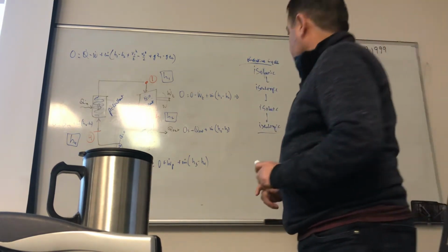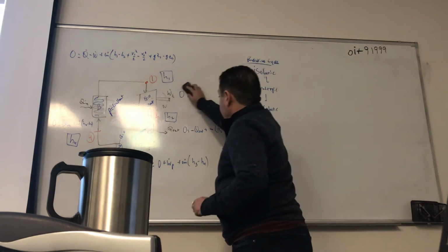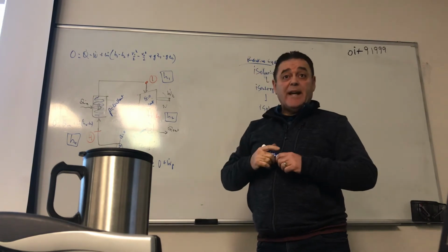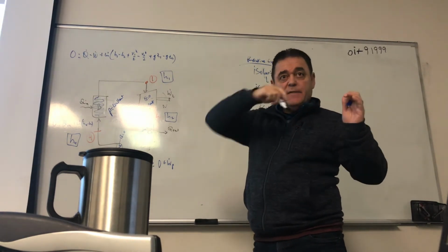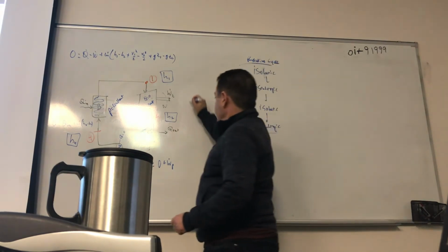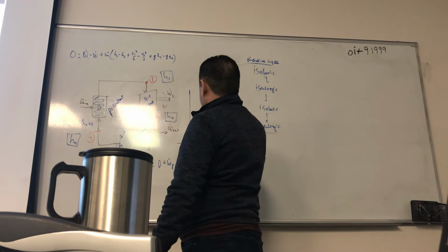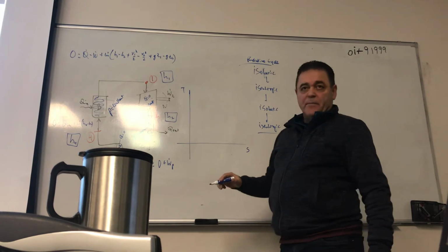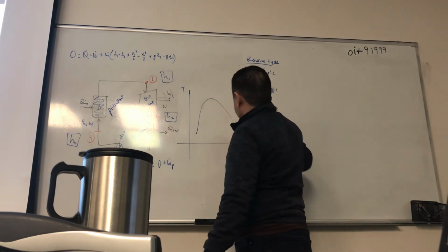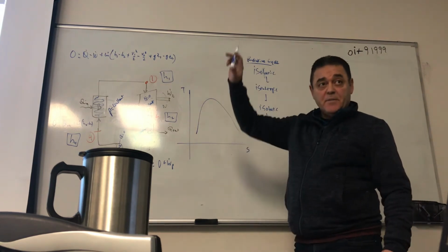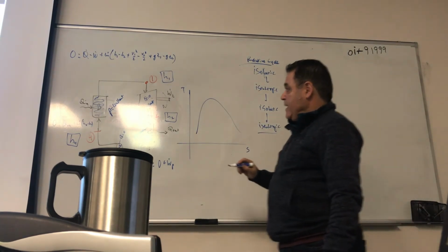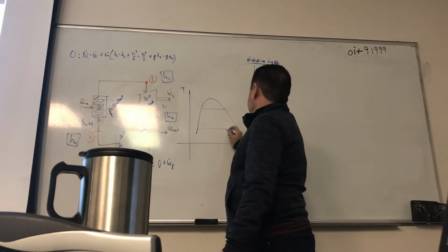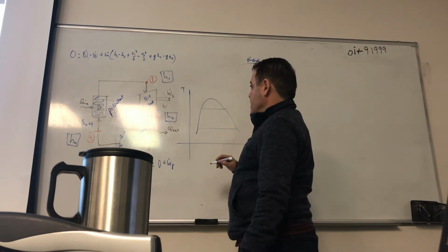Because we are dealing also with water that's being vaporized and it's coming back to liquid again, that means we're working in the vicinity of a dome, right? So if you look at the dome like this, I'm not going to do a PV diagram, I'm going to be doing a TS diagram because isentropic is easy. That means it's a vertical line, right? So typically what happens, remember you're working between 2 pressures, right? 2 pressures like this.